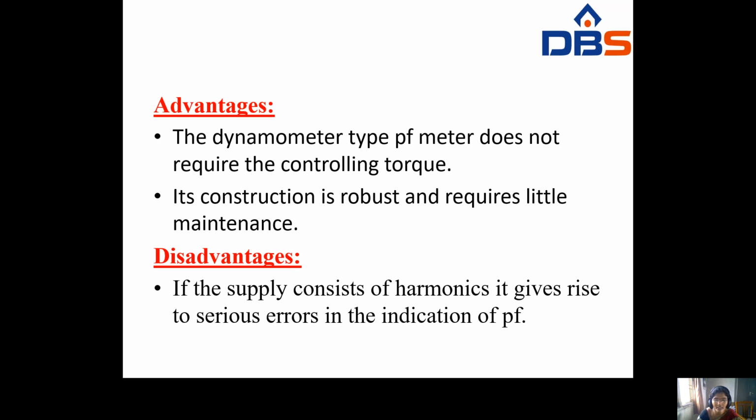Coming to the disadvantages: if the supply consists of harmonics, it gives rise to serious errors in the indication of the power factor meter. If, for example, the supply consists of harmonics, it causes serious errors in the indication of the power factor. So these are the disadvantages.